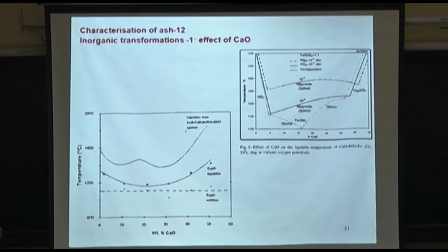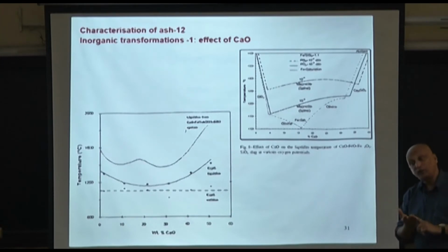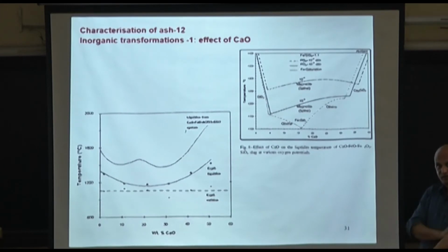Correct. Temperature, atmosphere, reducing versus oxidizing. How reducing? Because reducing means substoichiometric, right? Now, is it only a 0.3 stoichiometric ratio, or 0.2, or 0.9? Still, it will be all reducing. That is very, very important to know. And what else is there inside the composition?